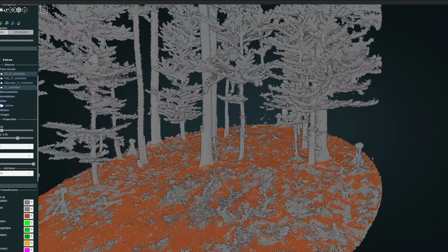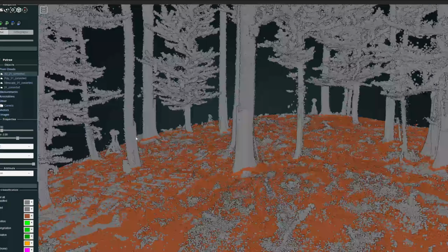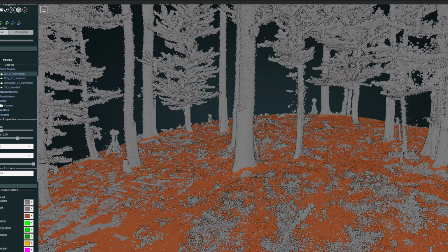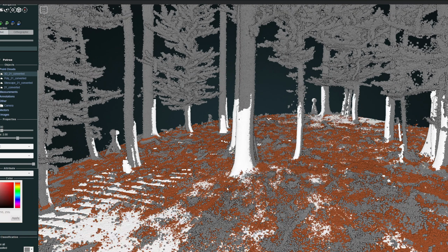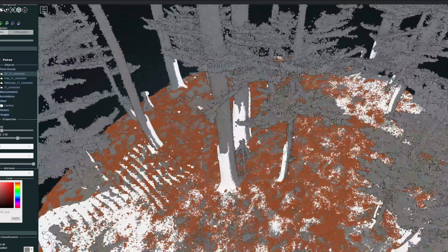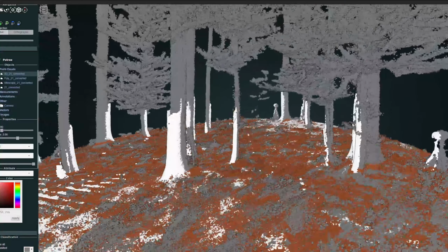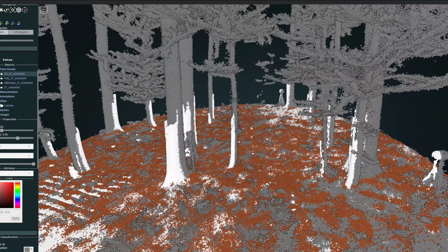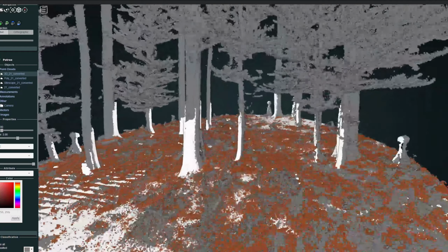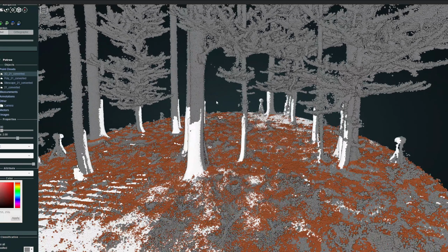There's a bit of a shift here, depending on which point cloud we're looking at, especially say this one right here. If I take my background one, let me just make this a set color so it pops out. You can start to see the shift that occurred there. Maybe the geometry is not quite perfect. That's an example of some of the mobile LiDAR algorithms, but this is also 2 years old. So collecting this with newer apps, newer versions of it, may yield different results. There's also not a lot of understory here, so it is pretty good conditions for terrestrial LiDAR.